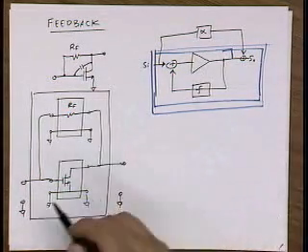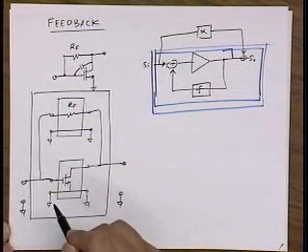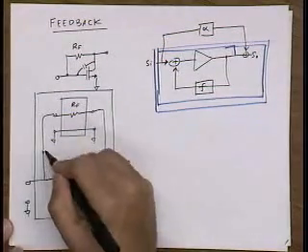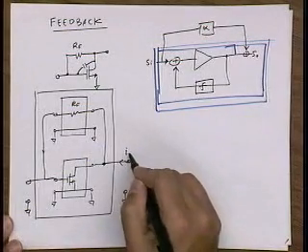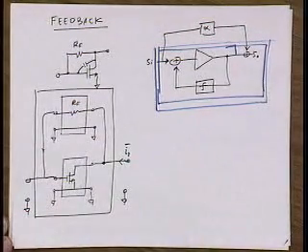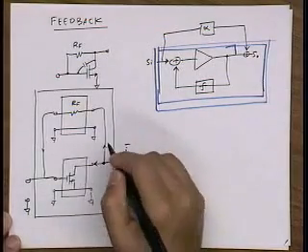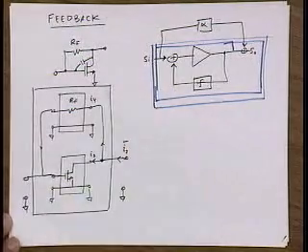And because here the voltage on the input and output are equal, of course, I'm feeding back a current signal. If I look at the actual, let's call this I2 bar, the actual current going into the net two-port, we can see that it's a sum of the current, let's call this I2, and let's call this I4.